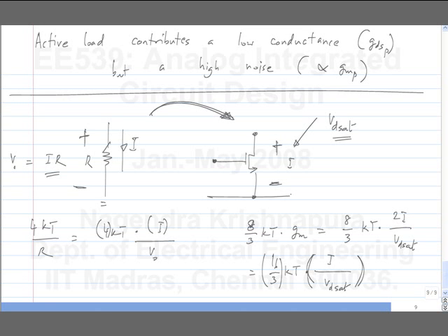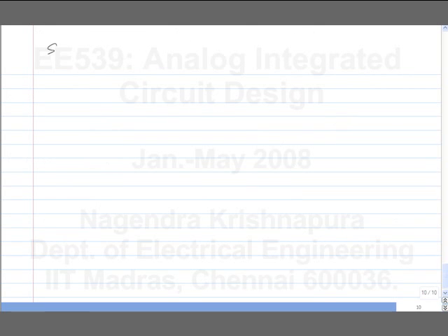Okay, this again you will find to be true. If you want low noise, you will end up having to bias everything at a high VD sat. Okay, which will compromise headroom. So just now I pointed out that the swing is VDD minus. So the swing limit in the problem was